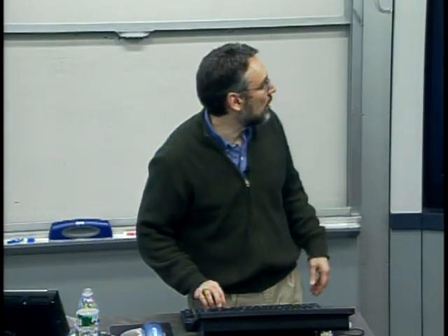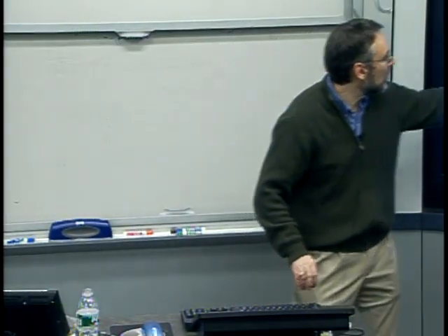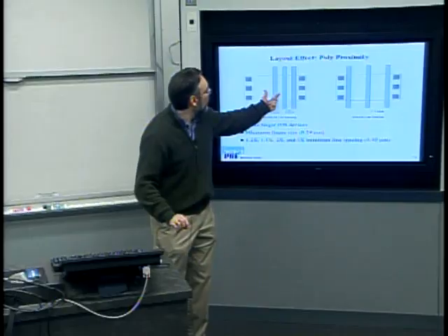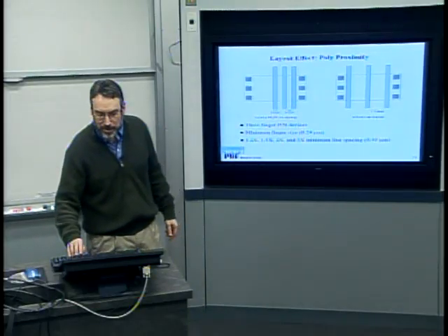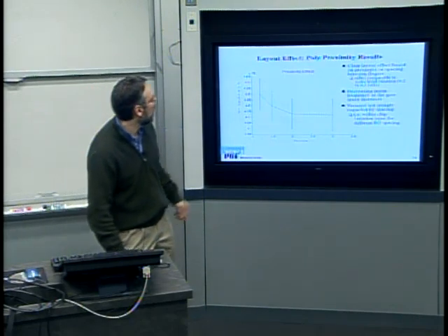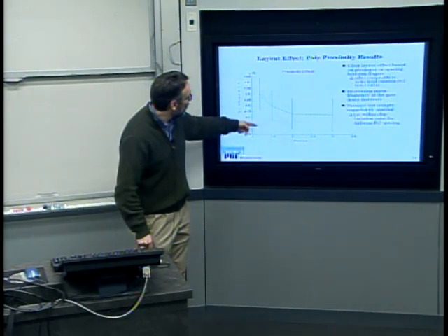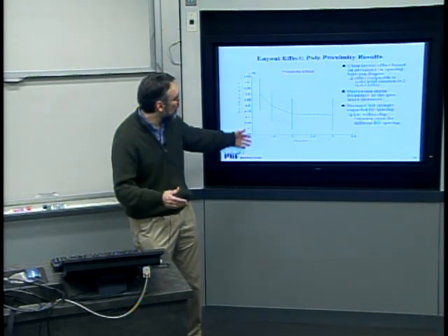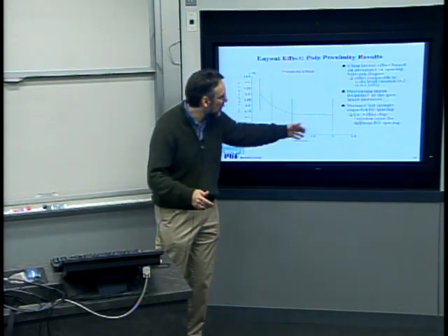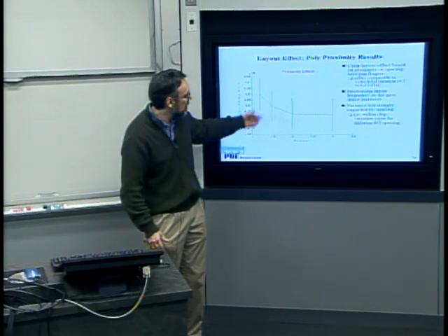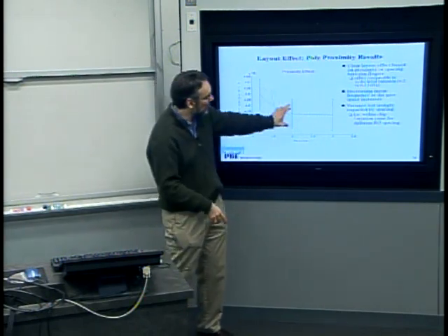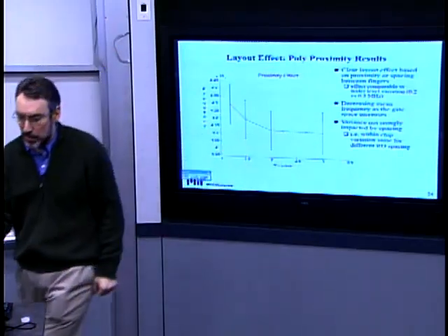That's telling us there's a different source of physical variation at work within each of the chips. And then you can also look for other systematic effects, things like the proximity of one poly finger to another can have photolithographic effects. In particular, that can result in an offset depending on whether I have 1 micron or 2 micron or 2x or 3x spacing between the devices. But in this case, the variation across many, many replicates of each of those is about the same.